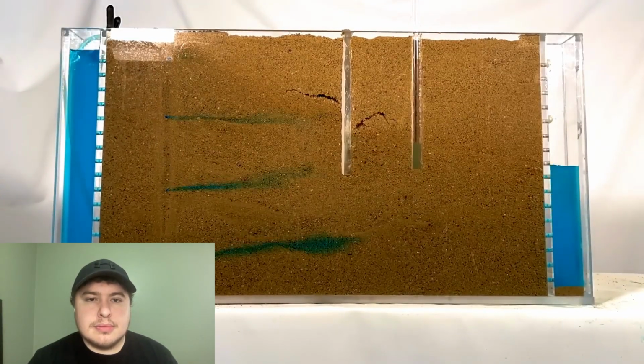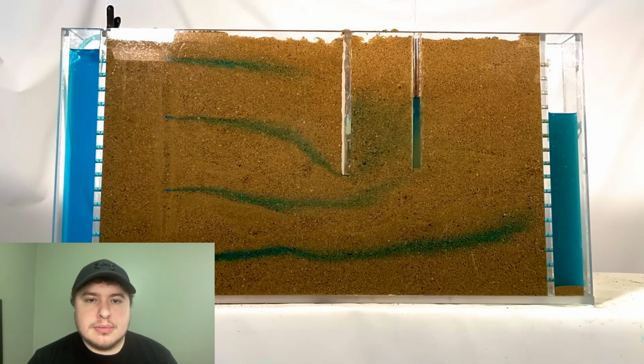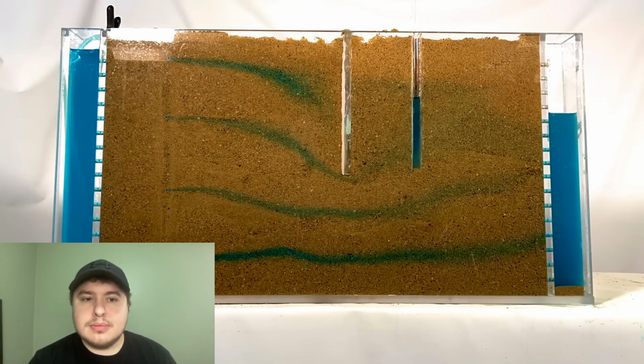But many don't. Cutoff walls can still reduce the volume of flow and the pressure, even if seepage can still make its way underneath. Let's take a look at the model to see why. I've added a vertical wall of acrylic below the upstream face of my dam, and we'll see how it affects the flow. The groundwater flow lines adjust to go under the wall and back up to the other side of the model. If you look closely, you'll see a slight decrease in the uplift measurement pipe below the dam. The only thing I changed between this model and the last one was adding the cutoff wall. So why would the pressure decrease on the downstream side?